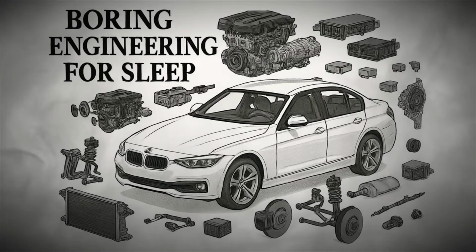The fuel pump is the next essential component, drawing fuel from the tank and pushing it through the lines toward the engine. In older cars, a mechanical pump driven by the engine was common, but modern cars use electric pumps mounted inside the fuel tank. Electric pumps provide consistent pressure and help prevent vapor lock, while also being cooled by the surrounding fuel.